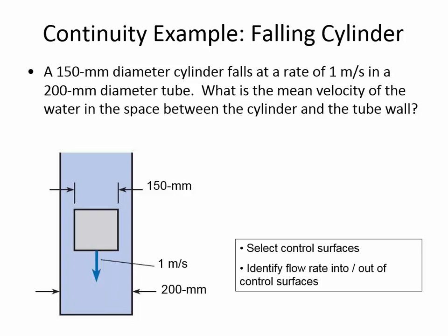That's right, collecting water and timing it. You guys have gotten really good at that this semester, haven't you? You've got someone who you know is old reliable with a stopwatch, someone who's really good at watching the water level rise. So you're going to know the volumetric flow rate. Q is a change in volume divided by some change in time. So that's how you're going to get Q.